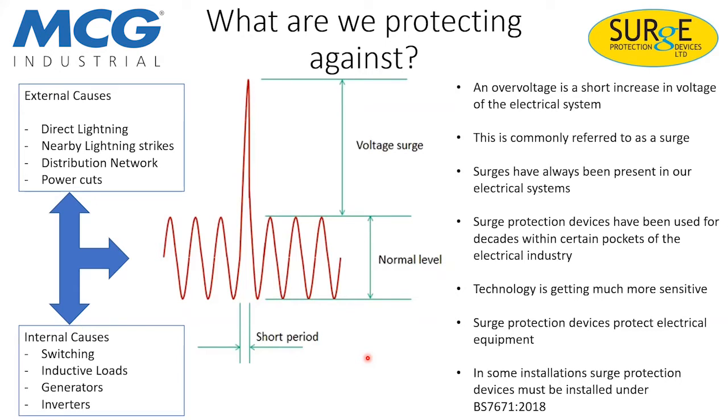So our surges can come from externally to the installation and internally. So if we start with our external, we have our direct lightning, which is what everyone thinks about, but I will be moving on to describing that a little bit more in a moment. We have nearby lightning strikes. We have switching surges caused by our distribution network, because as switching occurs in the network, we do automatically get surges appear. Everybody knows our standard voltage is 230 volt and it fluctuates from that, it's up and it's down, but we can get quite large spikes appear on that as well.